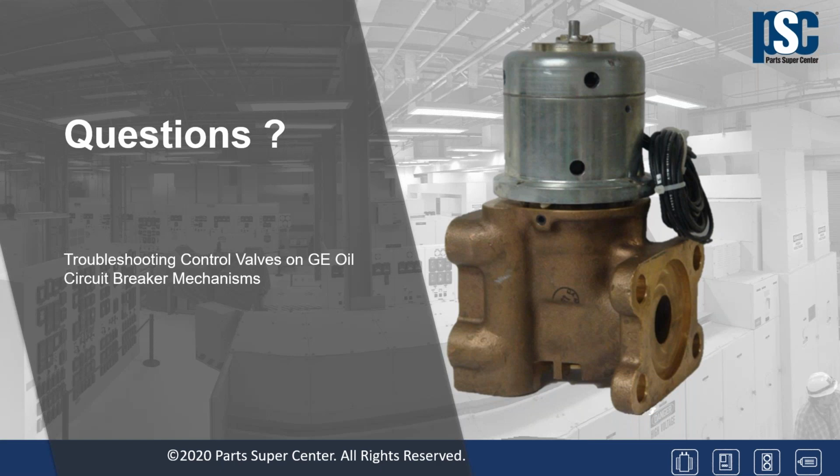Oftentimes customers will tell me they don't like to do that because the valve on the sump may not seal, and they don't like to do it in the winter as well. But I would argue that you should replace the valve and make sure that you drain the sump on a regular basis so you don't rust out your air receiver, or worse, blow air into the control valve, which not only can scratch that screen, get caught in that screen, but could also scratch the sealing surfaces of the main piston as well as the pilot armature seat.